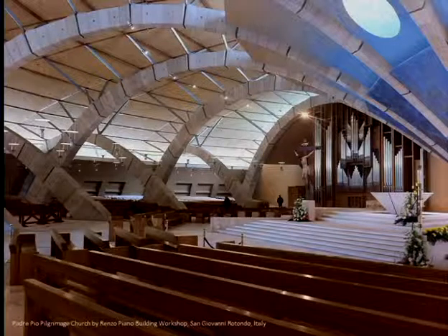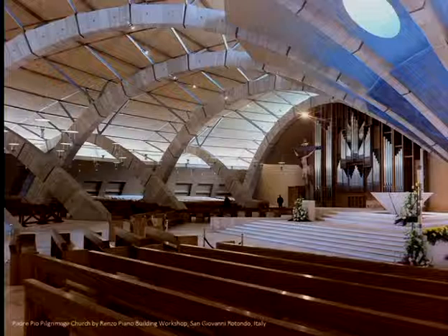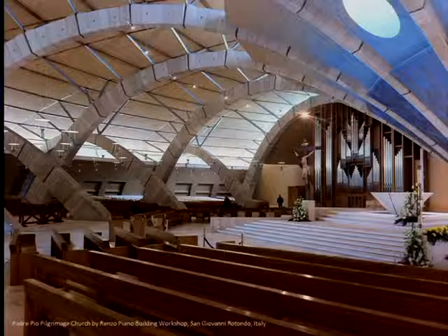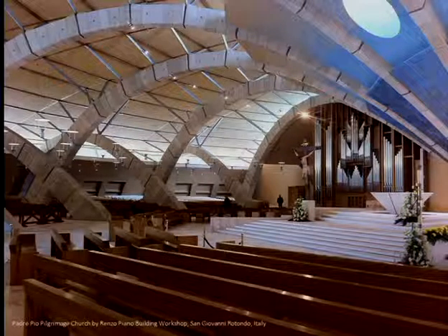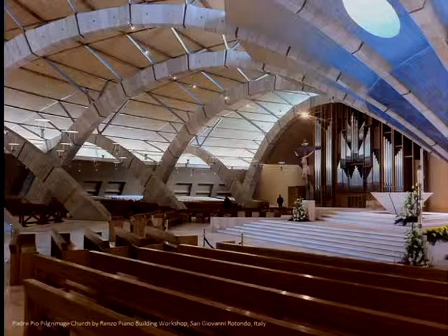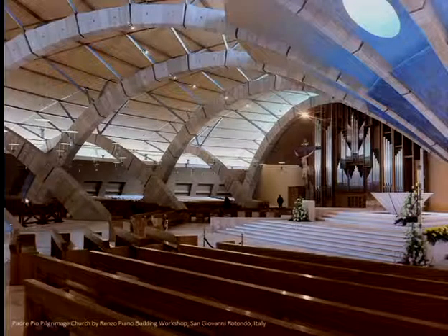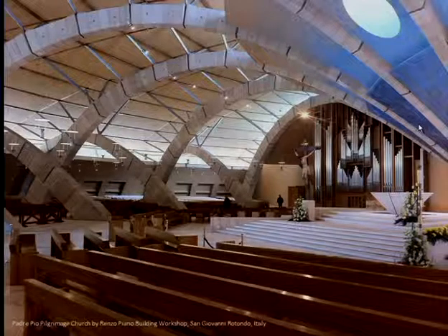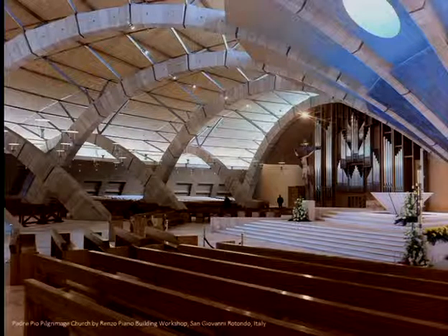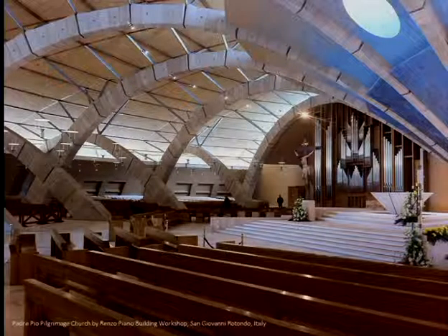Another way of using stones, let's say a dry construction technique, is this one, again in the south of Italy, Bari, because again stone is the most important material. This is a church designed by Renzo Piano, and in this case there are several arches. And the point is that, of course, they are compressed with some tension wires which are running inside the stone so that they keep all the units in position. But somehow we could say this is a dry construction, very engineered one, but dry construction.